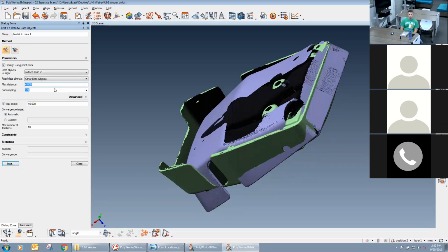I've seen on larger parts that it's harder to get the pre-align so close, so that number has needed to be adjusted higher for larger parts. I mean size of cars or larger. The next one, subsampling, is how many of the points are going to be used. It's 1/4 of the overlapping points.